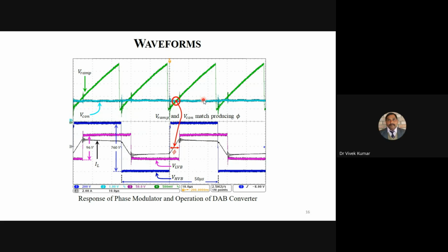So this completely depends on what your switching frequency is. If you tune the switching frequency, you can adjust this discharge cycle. Also you can adjust the injection of current. Generally it is done by a series resistance through your voltage source.